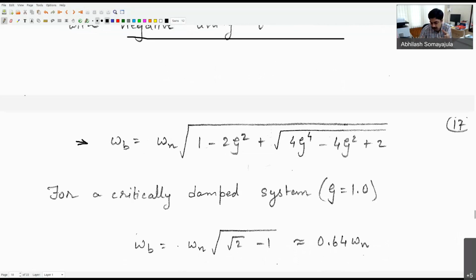So you can see that for a second order system, if I know the natural frequency and the damping ratio, I can specify the bandwidth. Okay, or in the other way around, suppose in a control systems engineer perspective, they would not want to specify where omega n would be, but they want to probably specify what the bandwidth would be. Remember that when we were doing successive loop closure, we wanted to ensure that the inside loop has a bigger bandwidth than the outside loop. Right? So sometimes we may not want to specify in terms of omega n. Rather, we want to specify, I want so much bandwidth on this system. Okay, and from that bandwidth and a damping ratio, I need to be able to compute what my omega n looks like.